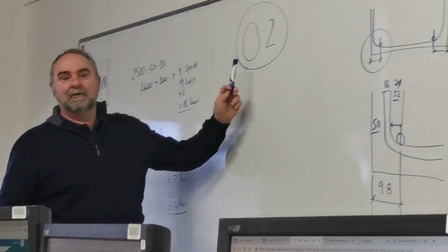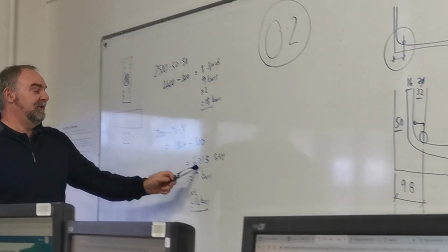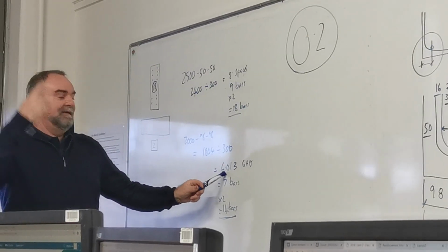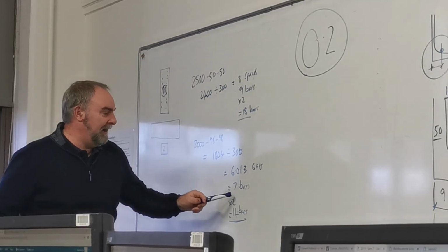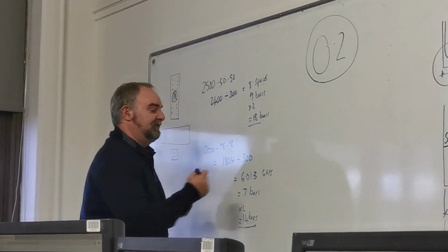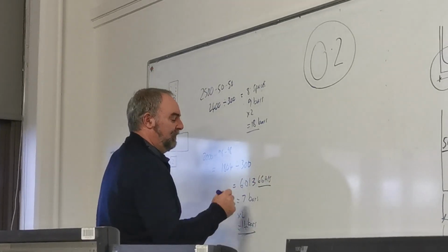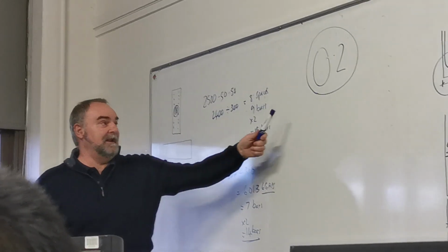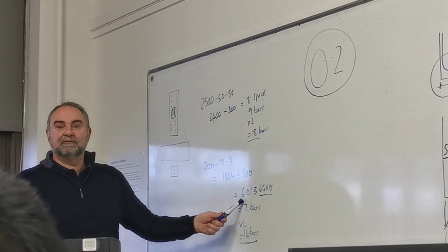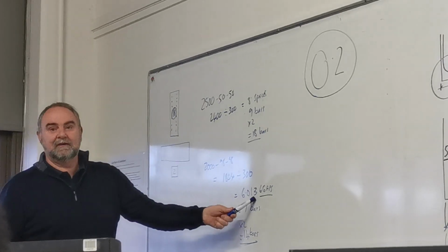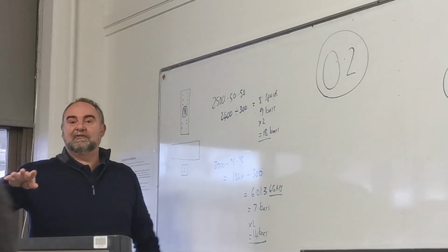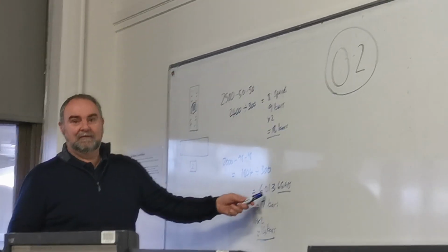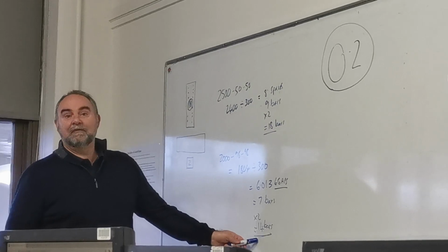If it's 0.2, if that was 6.2, you go up, right? So that would have been, instead of 6 gaps, it would have been 7 gaps in 8 bars. If that was under 0.2, which it is, 6.013, you go down. So it is acceptable in New Zealand to go down when it's that close. So you've learnt something already.